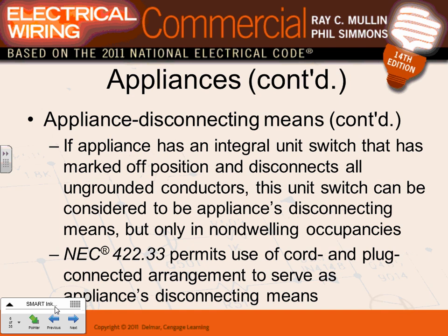We'll talk about disconnects and the site and so forth. Appliances means some appliances, guys, heaters and so forth, will have a disconnect as part of the appliance, right on the appliance, and you flip it and it says off. That qualifies on the appliance as a disconnect. Like heaters, notoriously famous of them, you have a switch that qualifies as a disconnect. Cord and plug is also a disconnect.